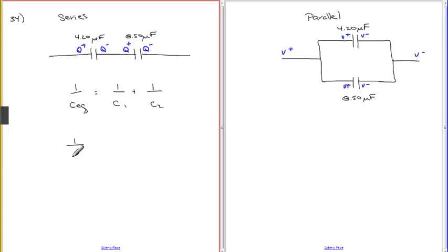So in this case, for the equivalent capacitance of the two capacitors in series, we take 1 over those. And I'm just going to include the numbers and then put the microfarads in at the end, as long as they're of the same order. If they're picofarads or nanofarads or whatever they are, you don't have to carry all that through until the end.